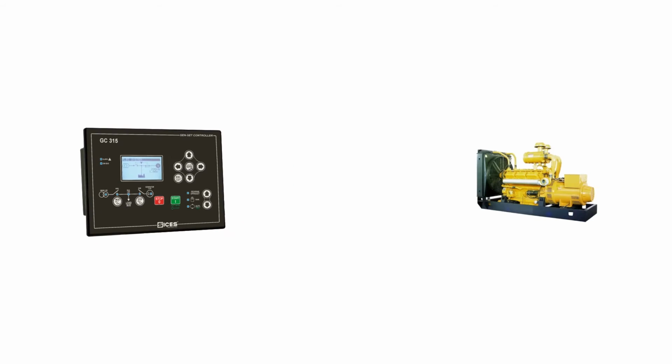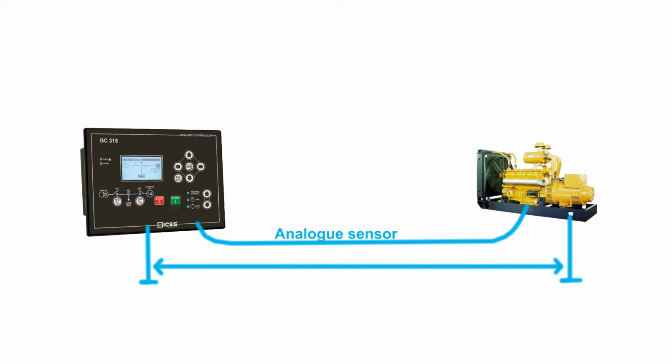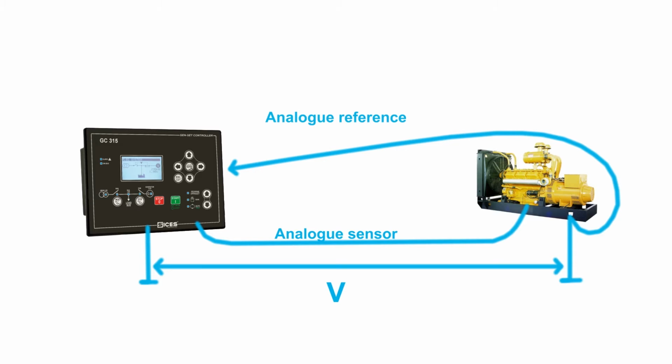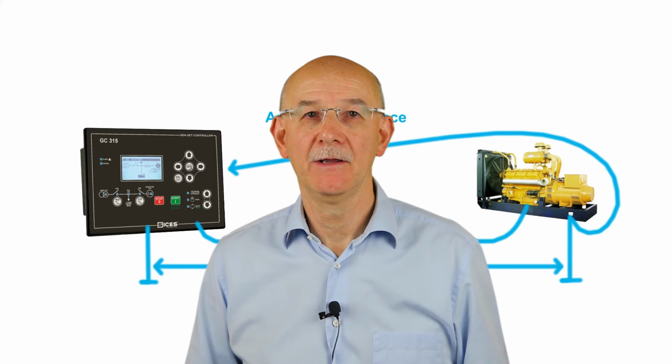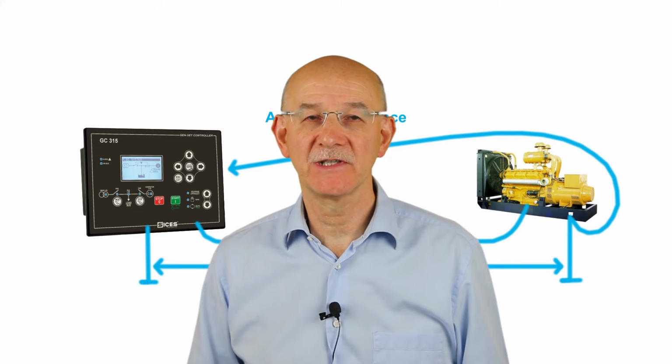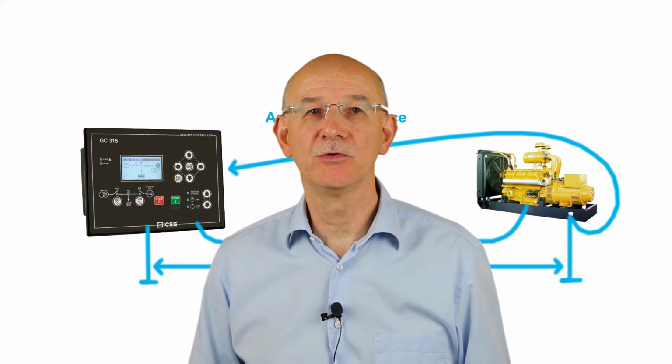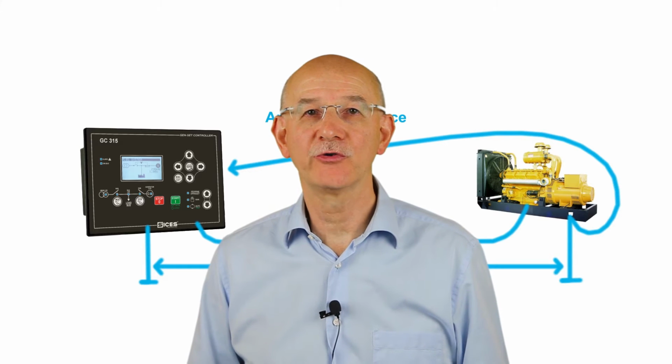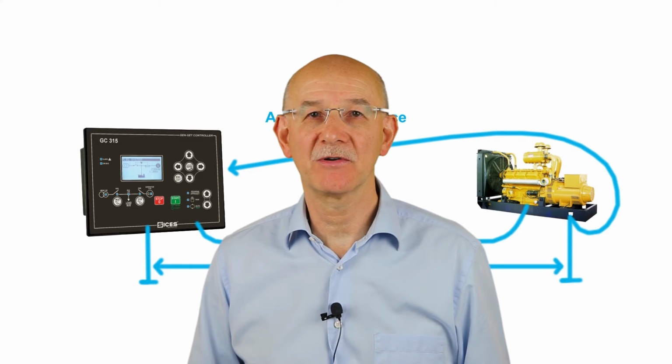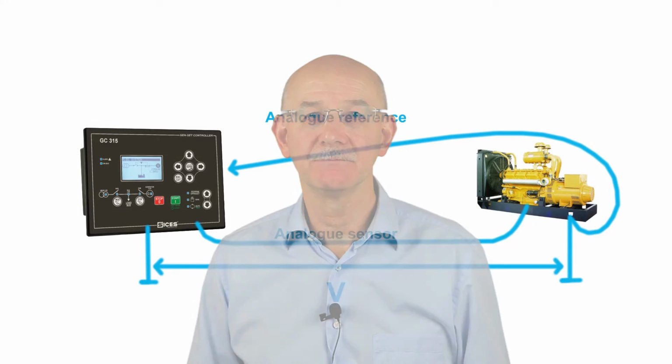Depending on the connection, a steady or transitory voltage can develop across the engine and the controller ground. Usually, sensors are cabled only by one wire, and this voltage can influence the resistance measurement. It is not mandatory to use this input. In this case, a good ground wiring system or two-wire sensor cabling should be provided. If not used, JM1 must be connected to ground.